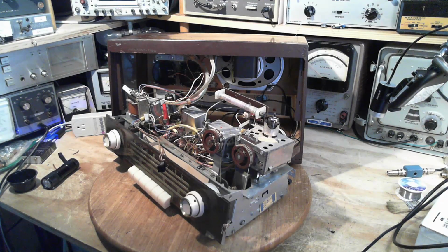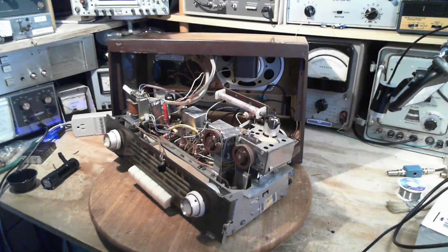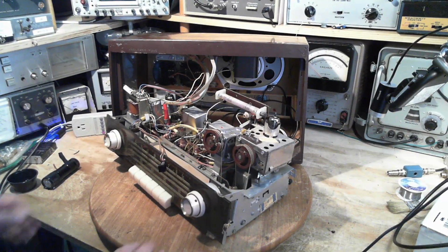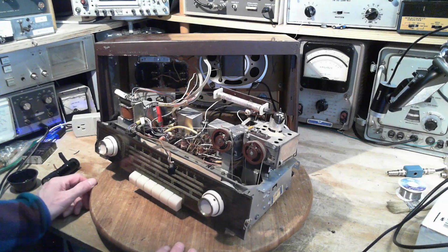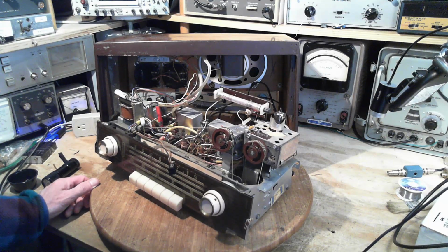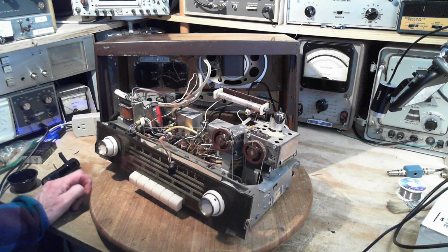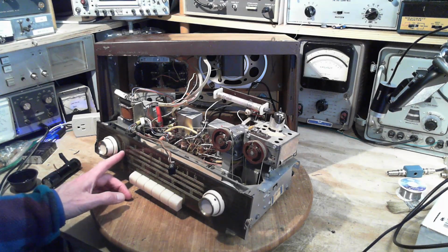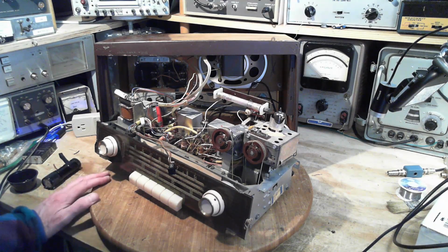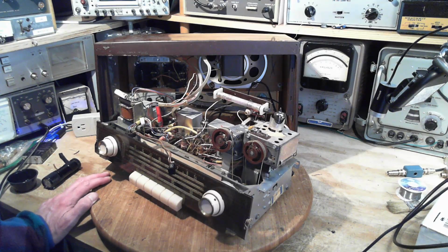It's April 26th. So what it appears to me is happening with this radio is something strange is going on with the automatic volume control, or the AVC system, if I can call it a system, in the radio. On FM, it seems to be operating okay. The magic eye seems to respond okay. Maybe a little weak, but it's there. On the AM bands, some weird stuff is happening.